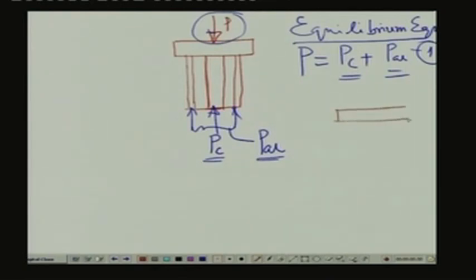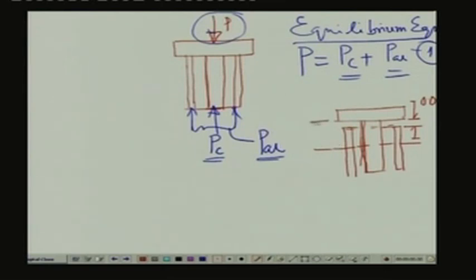So, this is the bearing plate along with the copper rod, and the sleeve is in this location, and this is the gap, since the copper rod is 0.05 millimeter greater than the sleeve. So, this is an exaggerated form, and let us say after deformation the bearing comes to this particular position. Hence, the deformation that the copper rod undergoes is this much.